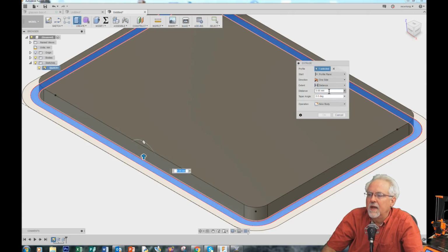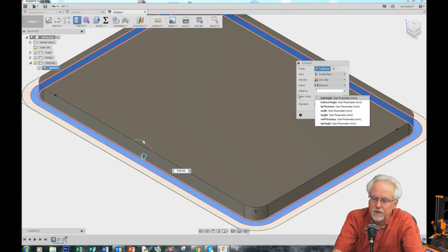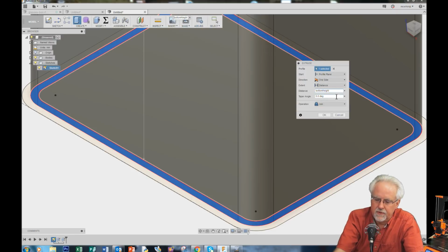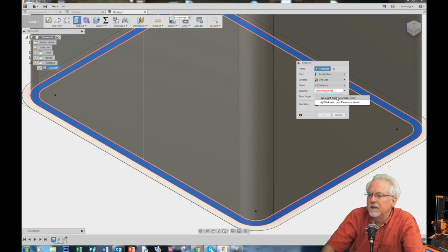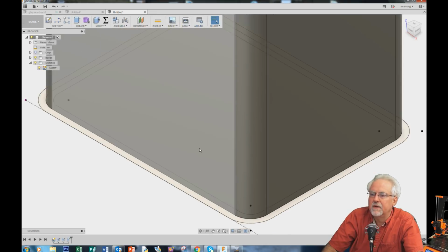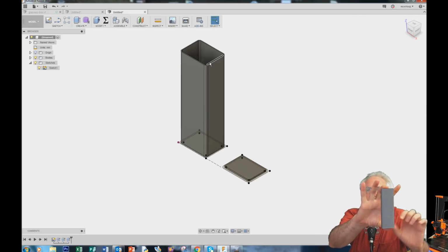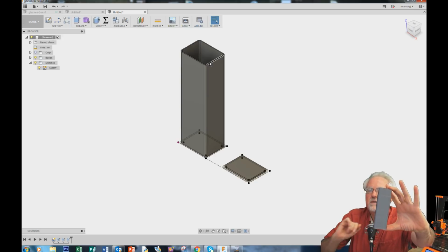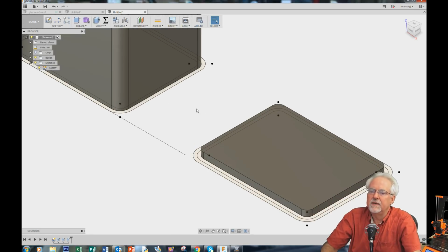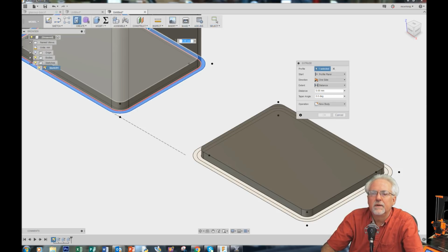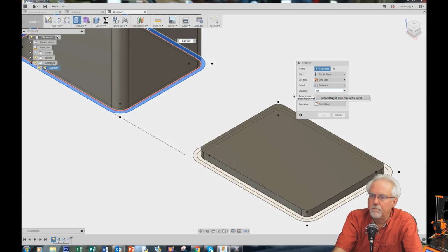We want to extrude. How high do I want it to come up? I want it to come up top height. Or, I'm sorry, that's bottom height, right? That's the bottom. My mistake. Bottom height plus what? Lip height. Bottom height plus lip height. Boom, look at that. That came all the way up. So this part from here to here is bottom height plus top height, and you get the whole thing. Okay, let's zoom back in. And then this one is going to be what? Can you tell me? Yeah, it's going to be just bottom height.